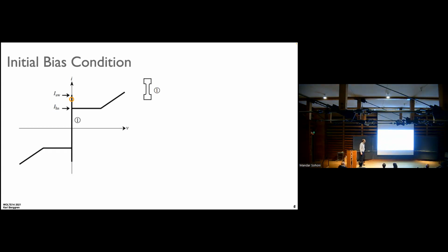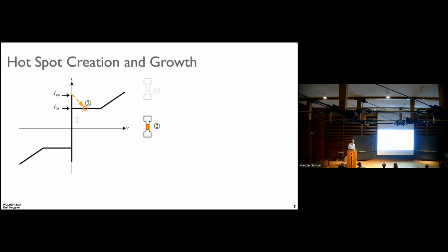It has a similar IV characteristic. It has a region here with 0 voltage in it, the superconducting region. If you overdrive this thing, it switches into a normal state. Just a hot spot of metal appears. There's no coherence, there's no tunneling across it of a quantum wave function or anything like that. Superconductor, resistor, superconductor.